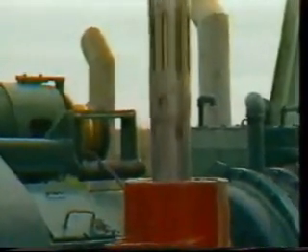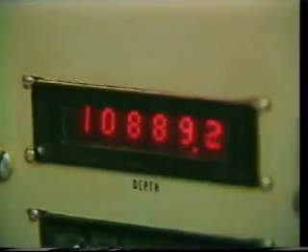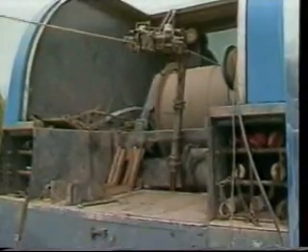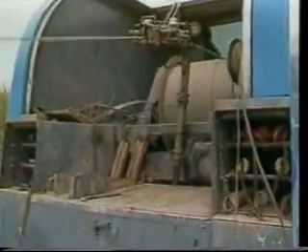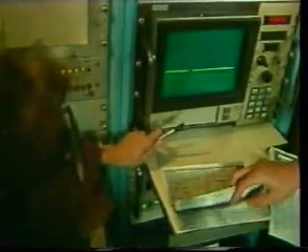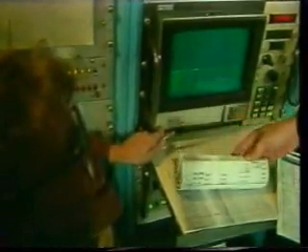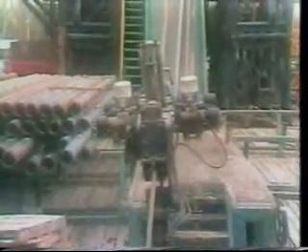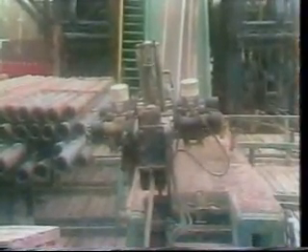The speed at which logging is carried out depends on the logging tools in the string. Each tool has a maximum speed at which it can be run. In general, the slower the tool is run, the better, although, of course, practical aspects such as the cost of rig time must be taken into account. The hole condition, tool design, lithology type, and concern for quality data should be the predominant factors in determining what the logging speed should be. If you are not familiar with the various logging tools at this point, don't worry. You'll learn more about them in GL 402.